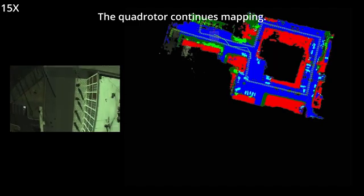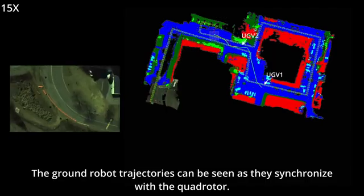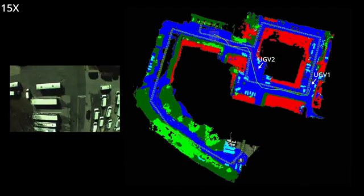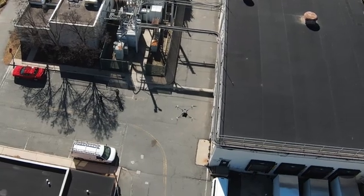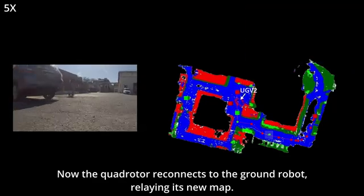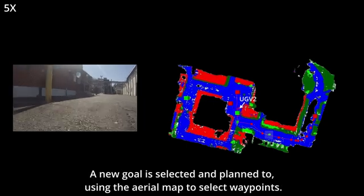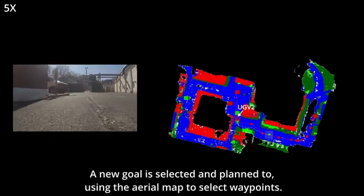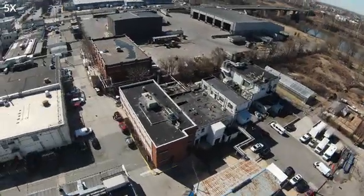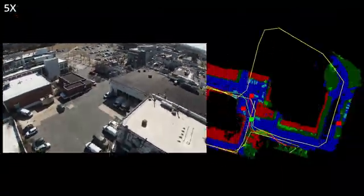Meanwhile, the UAV continues to explore and build a map, while receiving data from the UGVs that it can carry to other robots or to the base station. Once the UAV is back in communication with a ground robot, it sends updated maps, which have new goals, and the UGV selects one and plans accordingly. All of this happens completely autonomously. The base station acts as simply another node in the mesh network, but visualizes its best understanding of the system state for the human operator.